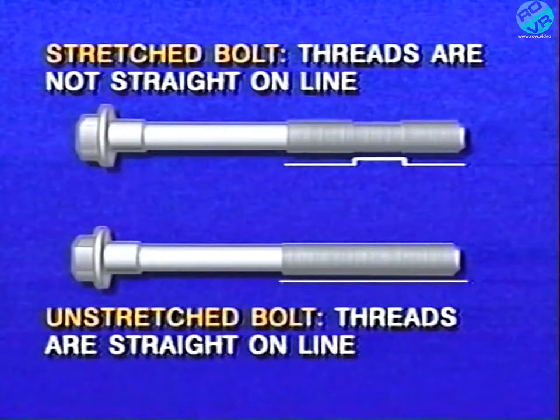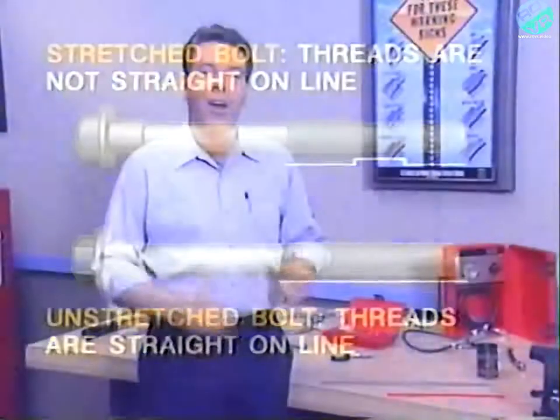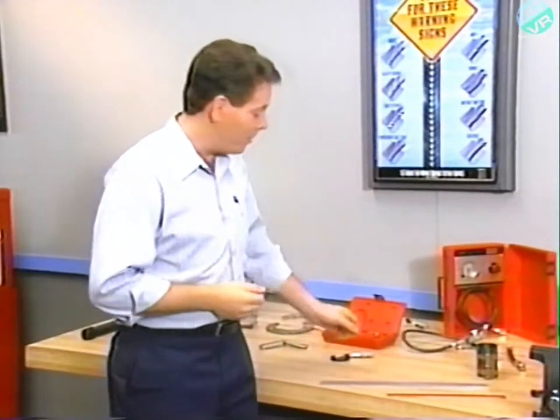However, if the threads are not aligned even with the straight edge, the bolt has been stretched or necked down. Because a stretched bolt is weaker, it should be replaced. Our next measuring tool is a micrometer, or a mic as it's often called.